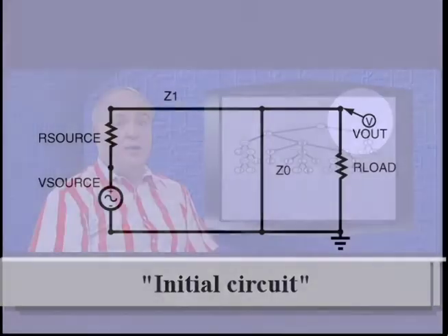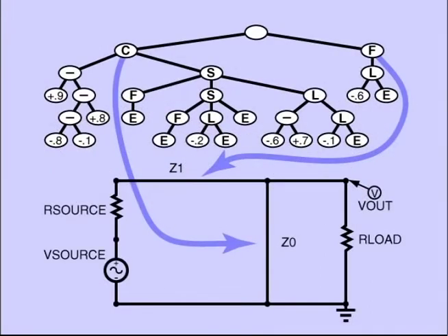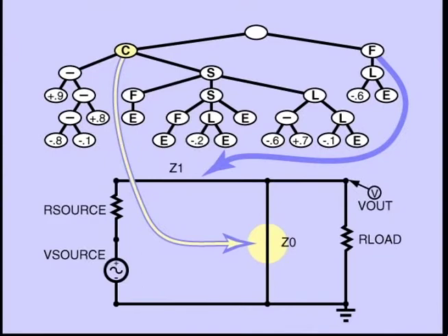Each circuit constructing program tree in the population contains component creating functions, topology modifying functions, and development controlling functions that grow a simple embryo into a fully developed circuit. Execution of the circuit constructing program tree begins with the capacitor creating C function associated with modifiable wire Z0, inserting capacitor C3 in lieu of modifiable wire Z0.